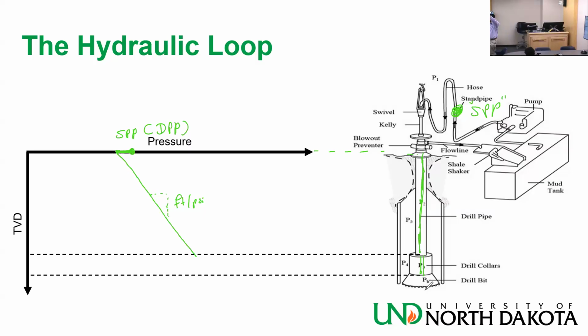When I'm going from the drill pipe to the drill collars, do you expect it to become bigger or smaller? He said that the slope is feet per PSI, so if you are thinking in terms of PSI per foot, inverse. Do you expect it to be a steeper line now, or less slope?